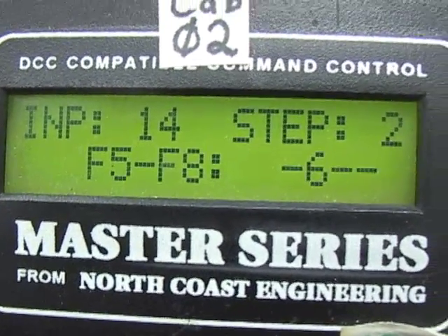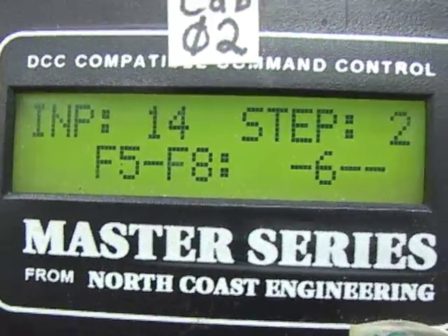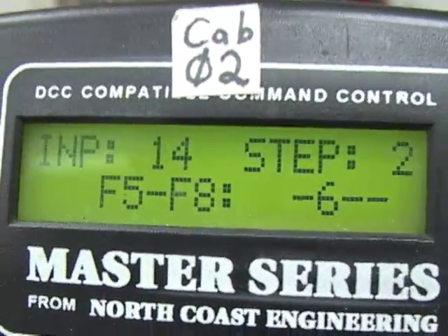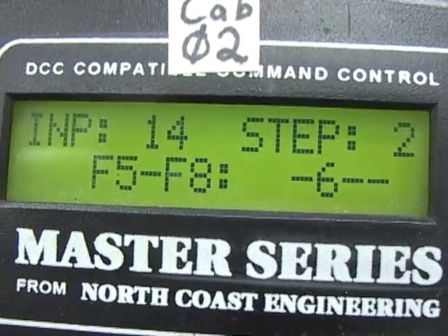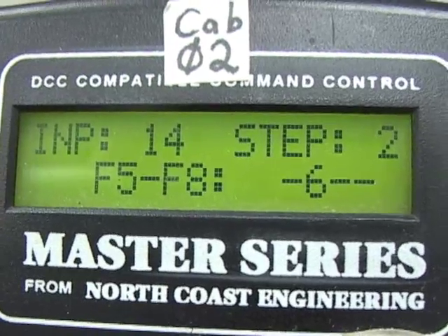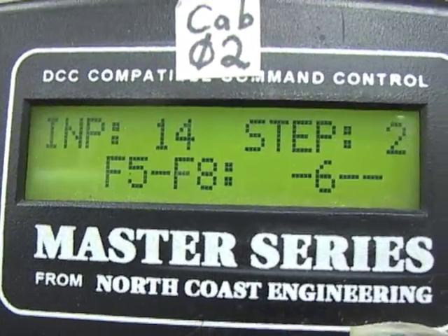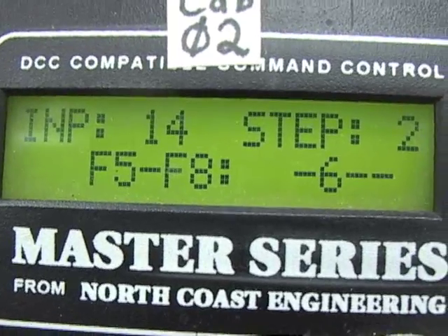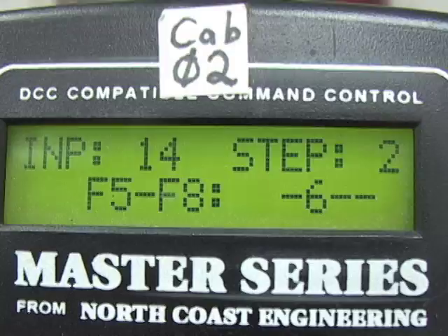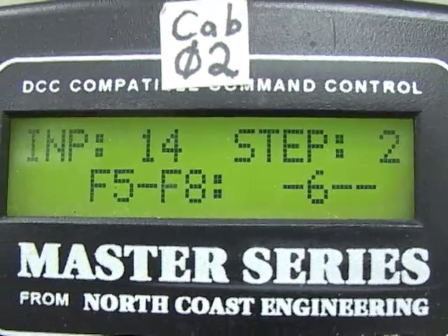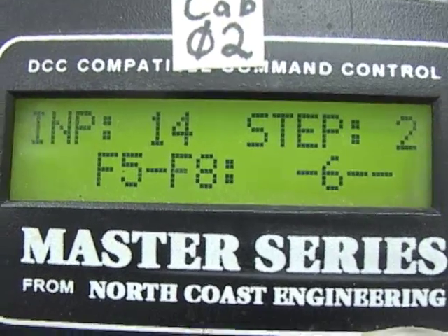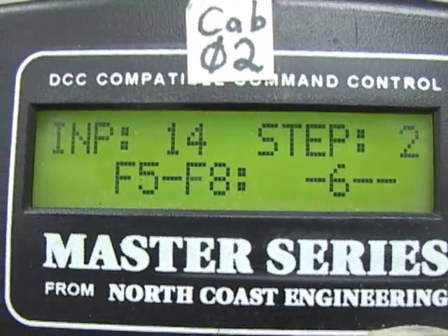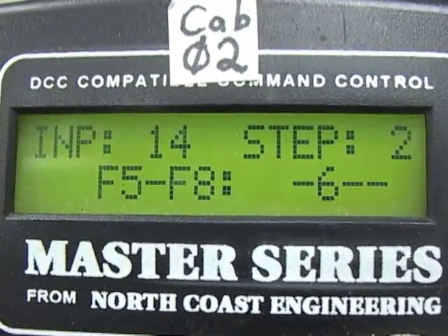Our next step, function 6 on this S-gauge engine turns on the rooftop strobe light, and it also happens to turn on the sound. In theory, you should use function 6 and 8, but there's a quirk in this decoder that if you do both of those, the sound turns back off. So again, I found by trial and error, this is how you turn the sound on. This is like an early generation Soundtraxx decoder. All these decoders have their own little quirks, so you can't program one quite the same as another, even though in theory they ideally should.